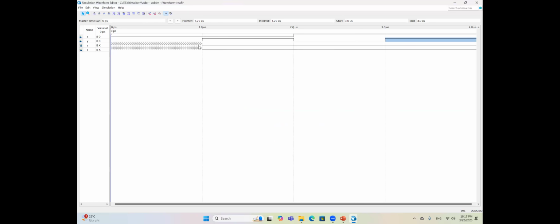We'll start with 2 zeros for the X and 2 ones. Sorry, this is the X again. So 2 zeros, 2 ones. Then we have 1 0 1 0 for Y. Before we do that, we go to simulation settings, 5th line, and remove this not opt. This is just for version 20.1, which we also recommend because it is the latest version. Set. Now we are ready to simulate.